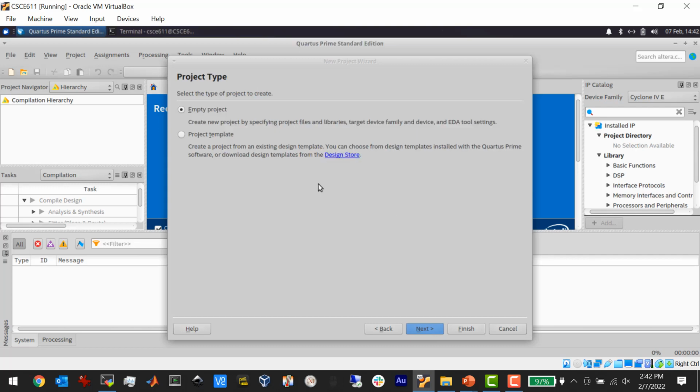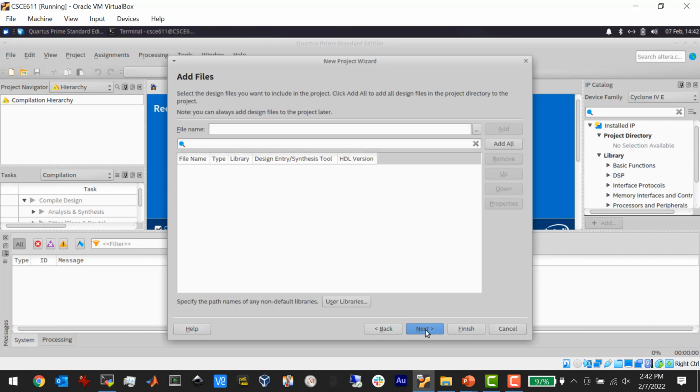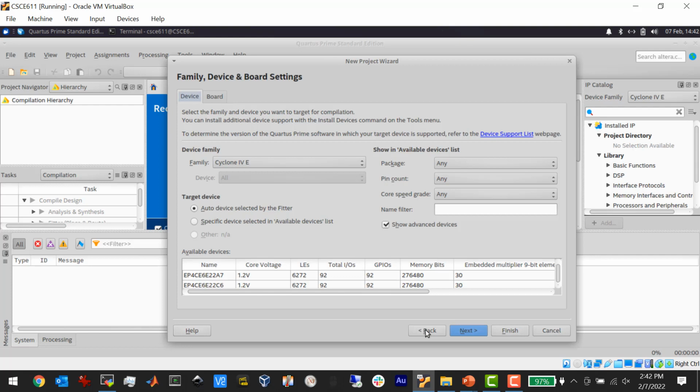Do you want to create it? Yes. We'll create it as an empty project. Okay, so here's the part that's a little obnoxious. There's a gazillion different FPGAs out there. There is a shocking amount. But the problem is whenever you have to set up the specific FPGA, not only the FPGA, but what package it's in and the speed grade. The package being the ceramic thing, the thing you actually see when you look at the board with the pins on it, the thing that's on the circuit board. You can have the same FPGA in multiple packages, which is true for any chip.